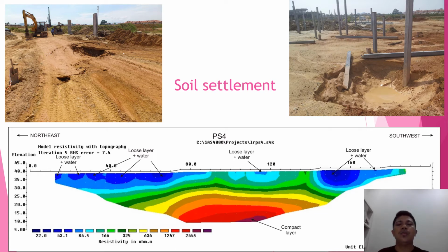So you can advise them on the thickness of soft material or loose layer, and then the engineer needs to make sure that the piling here is good enough, set on the hard layer.